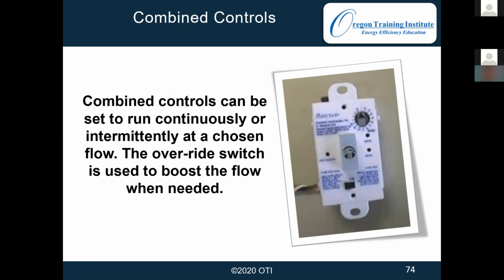But if they have a newer fan, we don't necessarily need to replace a brand new fan to meet ASHRAE. We might be able to just install a smart switch that can give it the features of an ASHRAE fan, like running on low speed continuously or running on a schedule to accomplish the same amount of airflow.